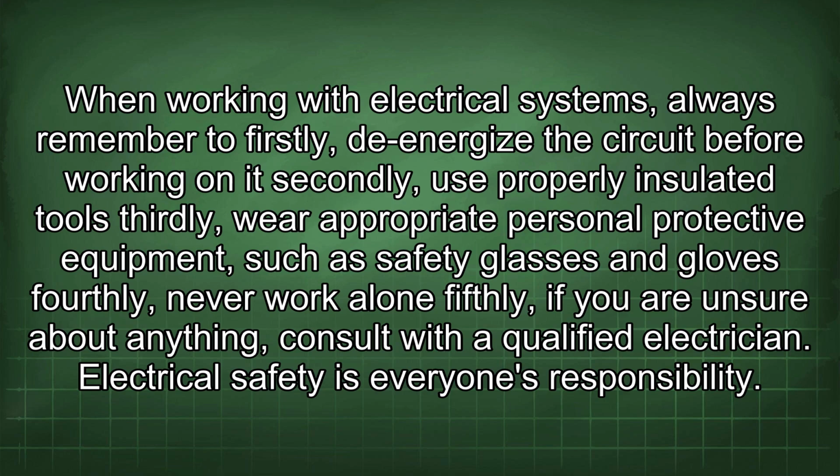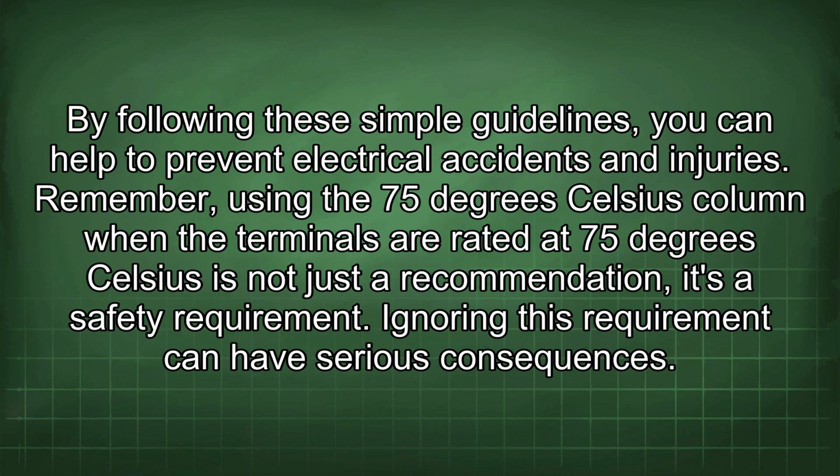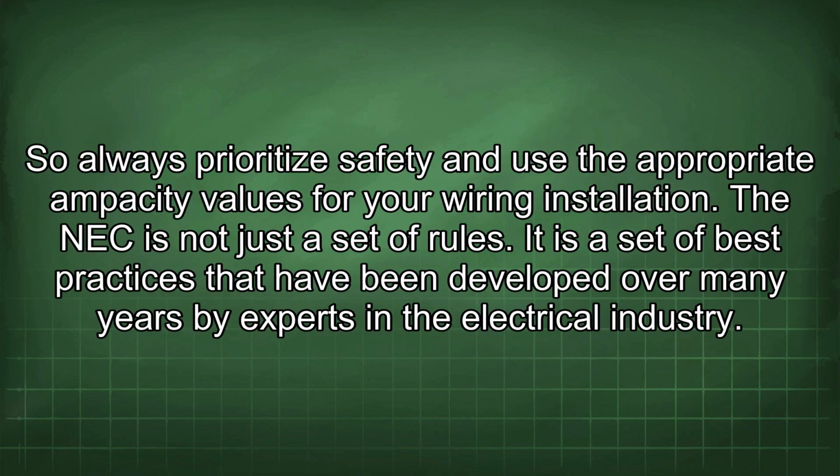Electrical safety is everyone's responsibility. By following these simple guidelines, you can help to prevent electrical accidents and injuries. Remember, using the 75 degrees Celsius column when the terminals are rated at 75 degrees Celsius is not just a recommendation, it's a safety requirement. Ignoring this requirement can have serious consequences. So always prioritize safety and use the appropriate ampacity values for your wiring installation.